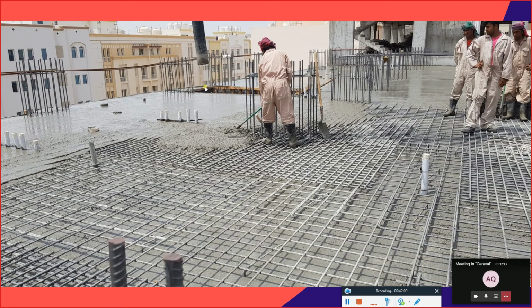After that, or even while pouring the concrete, we can use, or we should use the vibrator, so that will ensure that the particles will not stay in one position, especially the gravel. Okay, especially in these areas you can see here the reinforcement is a little bit far from each other, but in these particular places the reinforcement is very close. It means that the concrete particles, especially the large particles like aggregate, will get stuck. So I need to have the vibrator which will ensure that it will not stick in some way.